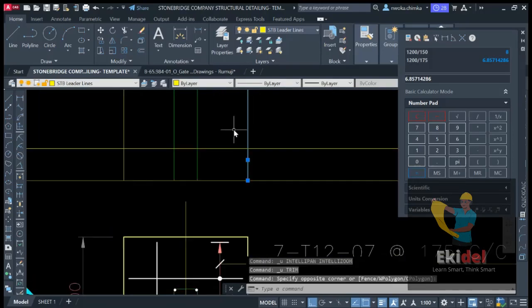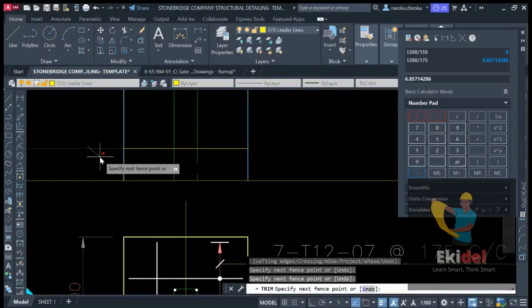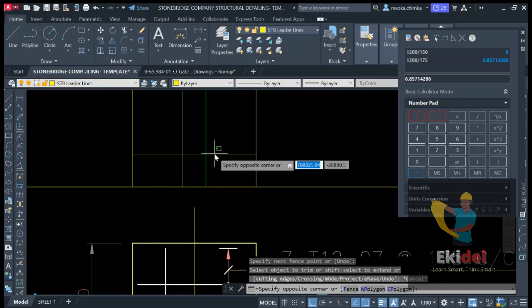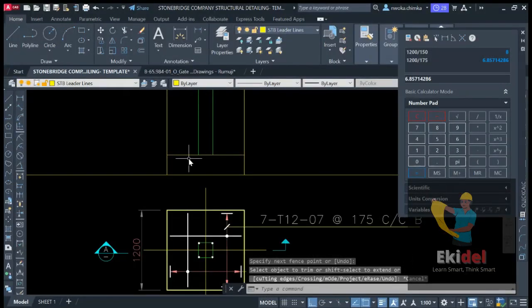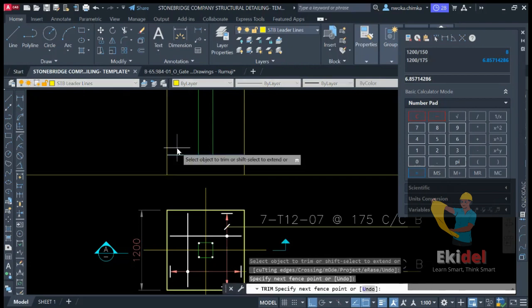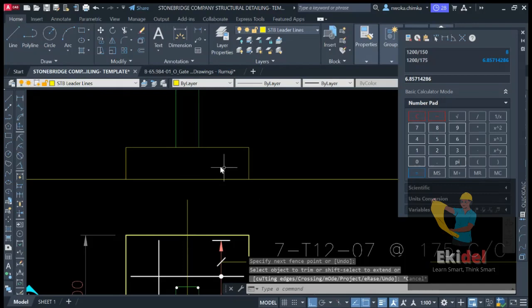Sorry, undo. Hold this place and hold this place and trim off this point and this point and this point also. And then trim over again and trim off this column entering the foundation right now. Okay, so hold here again and trim off again, TR, and trim off this and trim off this again. And then next to do right now is to offset our blinding.